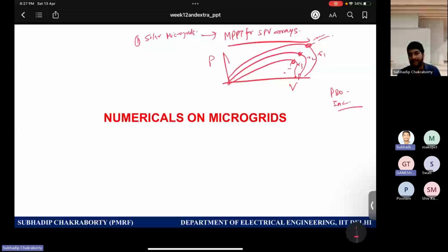It is, sir, maximum power point tracking means it should be mechanical. Yes, I am telling for solar. For solar microgrids, to achieve MPPT, are you doing any kind of mechanical arrangement or electrical arrangement? Mechanical means some tools like gears and all those things. Here, is it necessary, or are you doing it electrically by impressing a particular voltage using control? Electrically, sir. Yes. So solar microgrids are operated in MPPT electrically.